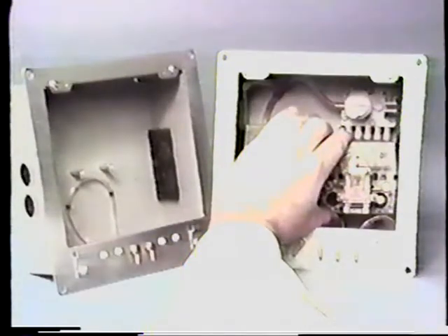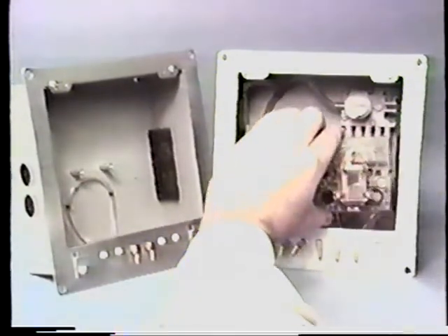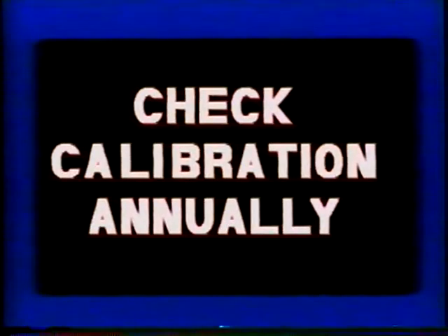Connect a receiver gauge to the outside air port and then to the return air port. Both devices should have the same output. After checking the alignment of the transmitters, remove the outside air transmitter and install it in the outside air transmitter mounting box. The calibration and alignment of the transmitter should be checked at least once a year.